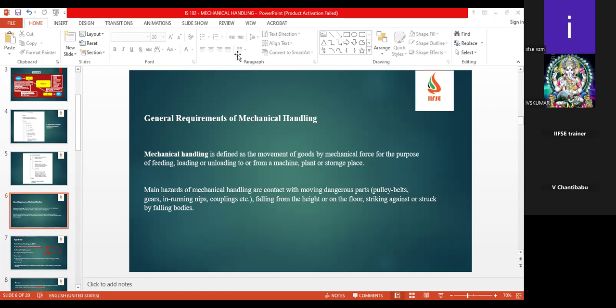UT is advisable, to check any internal cracks that cannot be seen from outside. It looks strong, but definitely there will be damage internally. That is also one check we should do. If the crane is 25 years old, then you should check all your hooks by UT.